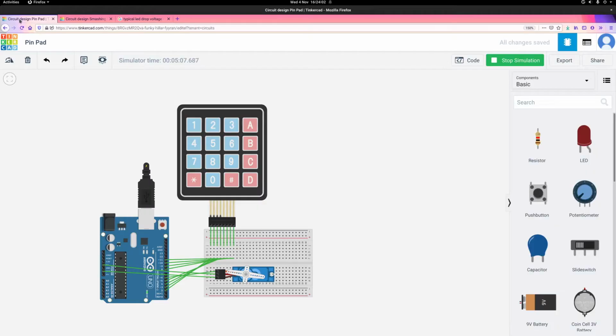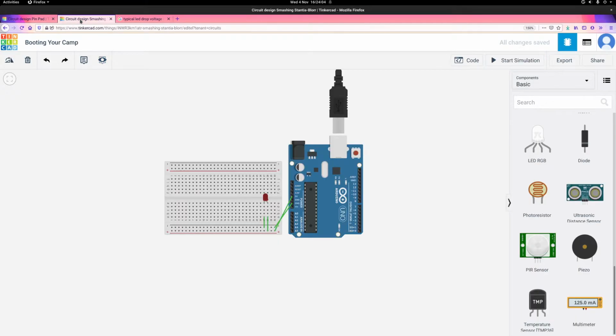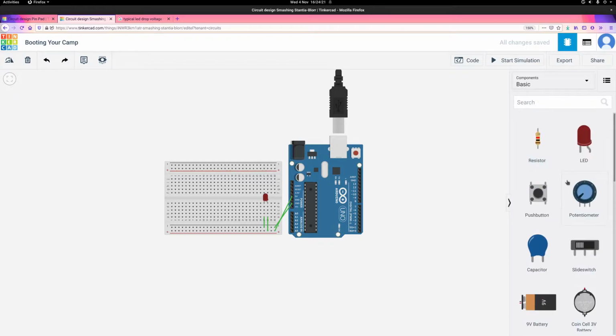So how LEDs work is they kind of just consume a fixed amount of voltage. And in our case, we'll assume on the safe side that it consumes the smaller amount. So we'll say this consumes 1.7 of the 5 volts, which means the rest of the voltage needs to be dropped across the resistor that we add. So, I'll type this in the Google Meet chat.